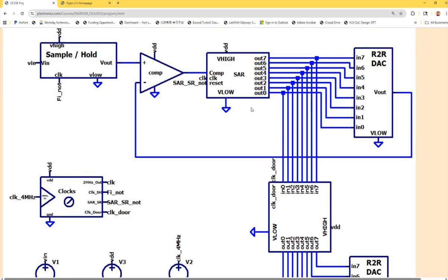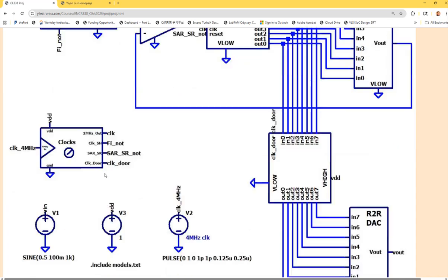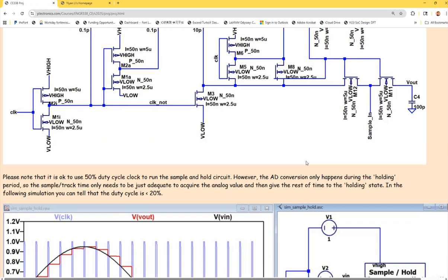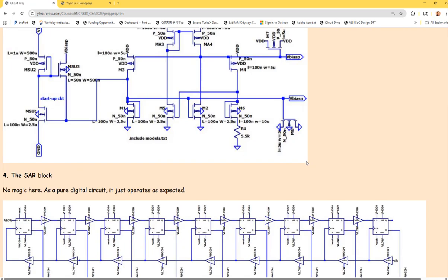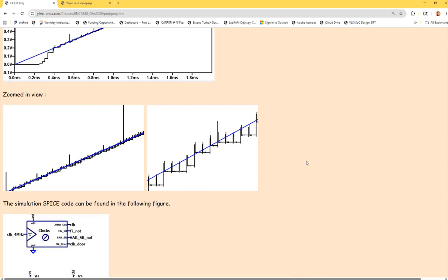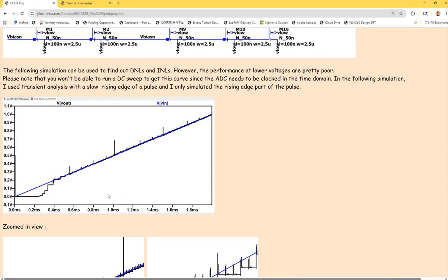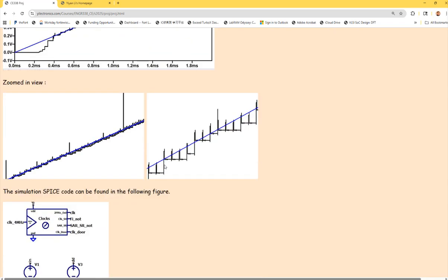So a very important one is the timing circuit over here. I'm trying to optimize it. The one we used in the last few semesters sort of worked, but it was always getting a lot of errors. You can see that's the op-amp issue for the lower voltages. It's not really tracking. But for the other ones, if I drew a line, it's able to track it. If you zoom in, you can see it has the steps to follow it.